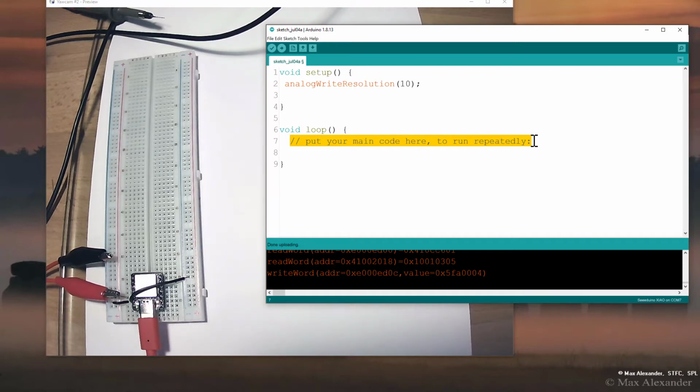So let's do that. We're just going to toggle a value in and turn it on and turn it off. It's literally going to be an analog write. The pin number is 0, and we're going to first put in 0, and that will start us out at 0. Then we're going to go analog write, pin 0, and let's put in 1000. So close to the limit, but not the very top. We'll explore those limits in a minute. And that's it. We're just going to repeat that. What do we expect to see? We're going to see the output toggling at the fastest rate that it can toggle, and we're going to measure that with the scope. That will give us an idea of the on time and the off time.